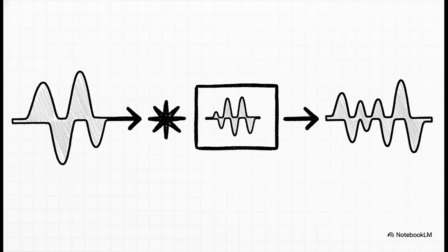And here is the ultimate mathematical payoff we've been building towards. If a system meets those two criteria, if it is both linear and time invariant, then the output, y of t, is simply the convolution of the input signal, x of t, and the system itself, h of t. That sliding blending integral we decoded way back at the beginning of this explainer? It's the direct mathematical consequence of a system being LTI. Convolution is literally the magical key to predicting the system's output.